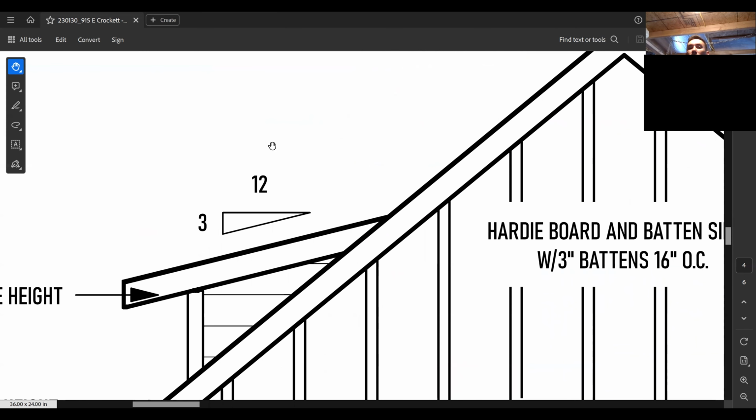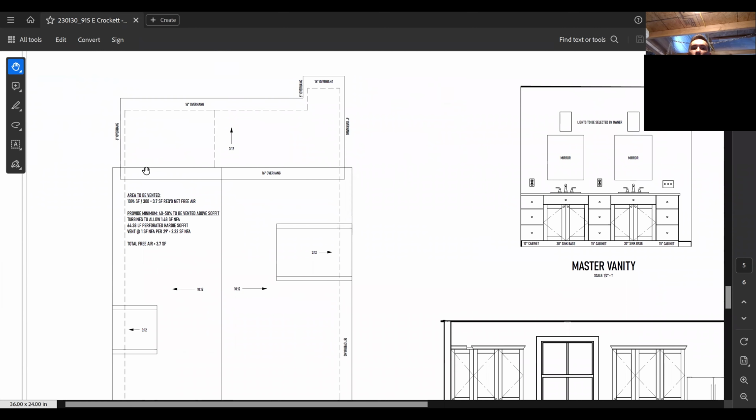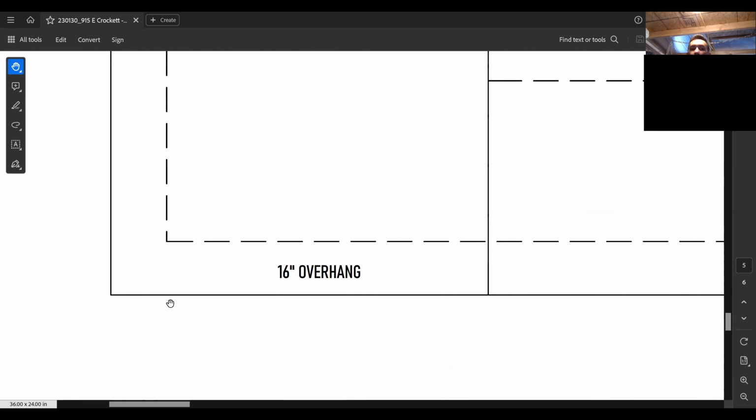The farther into the plan you get, the more it'll vary between architects or drafters. I put these things on the sheet because it just makes sense to me. The roof plan is going to describe a top-down view of the building outline and then the roof outline. So from the top down, this dashed line is the building framed dimension edge, foundation edge, if you will. And then the solid line is the actual edge of the roof.